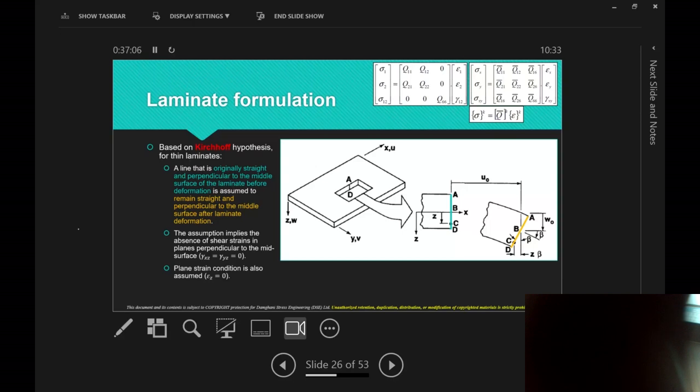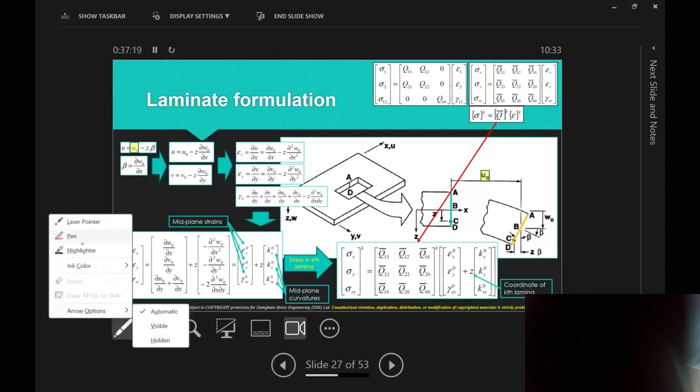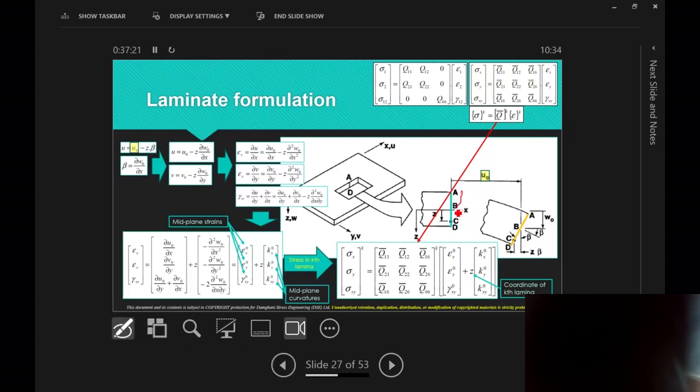But in reality, they call it zigzag theory. That plane, yeah. Not good, is it? That could be like this. That could do that. But if you don't have shear, or the shear is insignificant compared to bending, you don't have to worry about it. Which is 90% of the time, that's true.